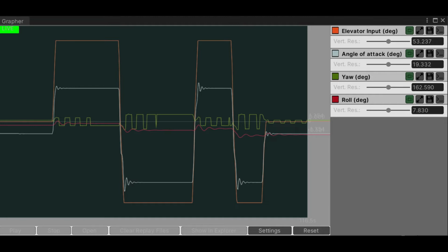It has also been proven, based on the showcase graphs, that the sign of the change in the trim of angle of attack is consistent with the sign of the elevator input, and that the aircraft pitch response is consistent with the change in lift on the tailplane.